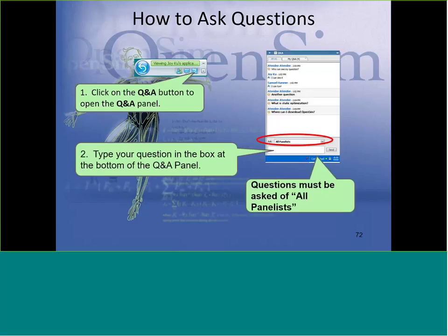So I don't necessarily recommend adding a lot of wrapping. Wrapping just makes it more complicated. Wrap where you need to, but in some cases it may be better to eliminate wrapping. Or maybe you just analyze a portion of the motion where the knee is really flexed, and then you might need a different wrapping surface than what you would need when the knee is extended, for example. So adding wrapping doesn't always help you. Right.